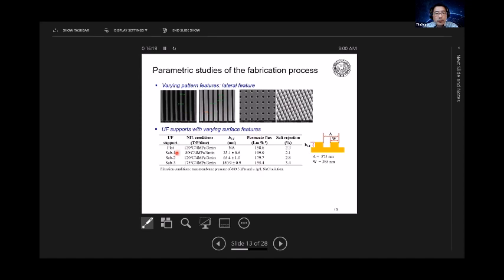And then we grow essentially different pattern heights. We take the grating pattern and pattern it using imprinting lithography, looking at different heights, right? These are the final performance data, which I'll again show shortly. So the pattern we look at here has a periodicity of about 570 nanometers. It's very small, and the width of the line is about 365.